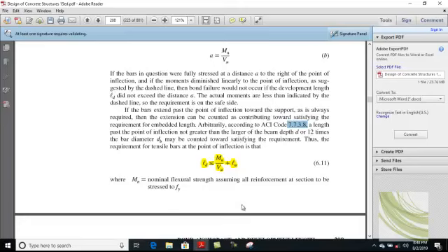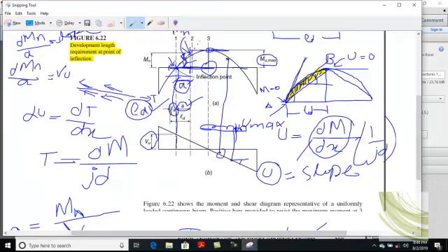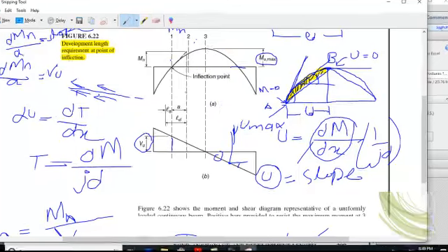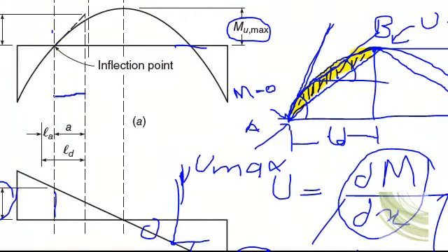Thus, this basically means you see this kind of relationship, clear, that this A is basically a distance at which you can say your whole bond, your bar stress, is produced. So this is a kind of embedment length, a kind of embedment length.